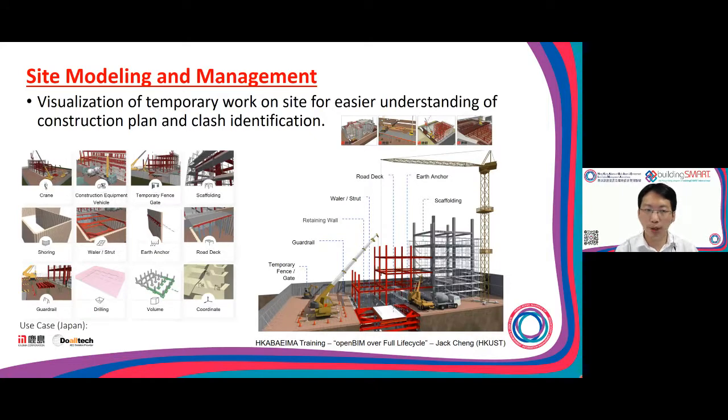I would like to go through a particular case in Japan about how they use an openBIM model to support construction. This is a project with an IFC model. You can see that this is an IFC model with all the details like scaffold, the anchor, etc. They model not only the building itself, but also the temporary work in IFC. And through this, they can generate the 4D visualization for constructability analysis, etc.